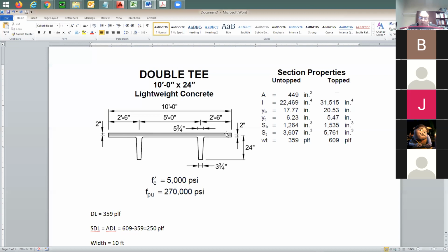Now add some loads from the top. Now the beam is not moving because I decided just to keep it in place. Something that we usually don't do, but I just decided to keep this beam or double T in place. Now, this additional concrete topping is not doing anything to the beam because the beam now is shored, supported.